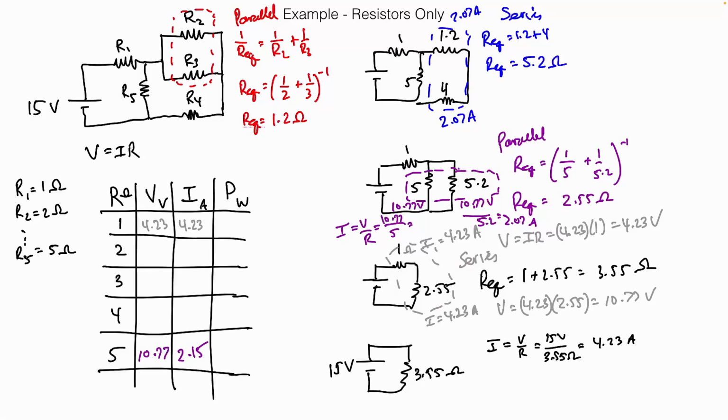It's Ohm's law and the rules, like what is the same and what is shared in parallel and series. So conceptually, you need to hold in your head Ohm's law. You need to remember that for a series connection, current's the same, and for a parallel connection, voltage is the same, and apply those rules at every point of your circuit.